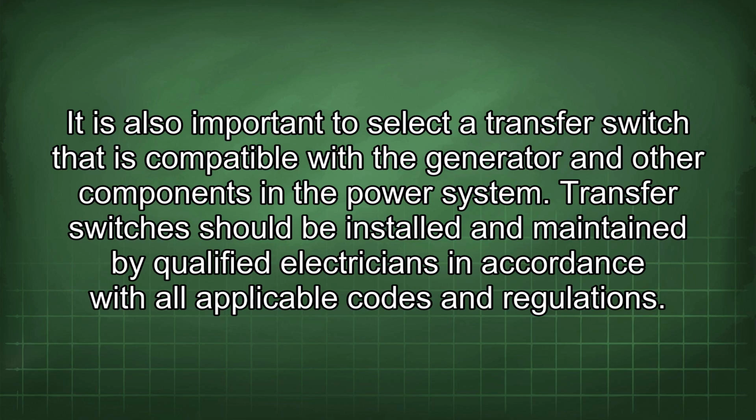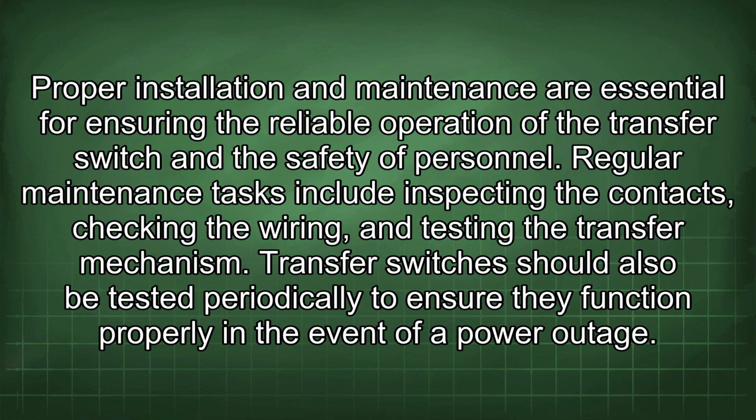Transfer switches should be installed and maintained by qualified electricians in accordance with all applicable codes and regulations. Proper installation and maintenance are essential for ensuring the reliable operation of the transfer switch and the safety of personnel. Regular maintenance tasks include inspecting the contacts, checking the wiring, and testing the transfer mechanism. Transfer switches should also be tested periodically to ensure they function properly in the event of a power outage.